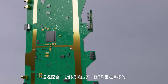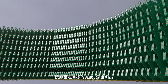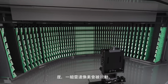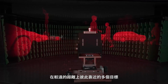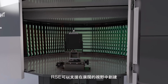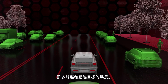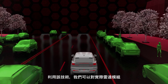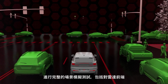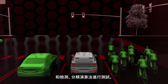Together, they generate a realistic outline of a 3D radar object. Items are represented by multiple pixels according to their width, depth, and height. Multiple objects close to each other at a farther distance will become separate as they get closer. Pixels work together to create a scene with many static and dynamic objects across a broad field of view. Using this technology, we can emulate complete scenes to the physical radar module, testing the radar front end and detection and categorization algorithms.